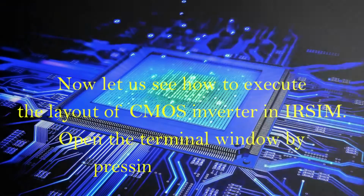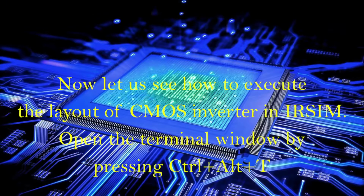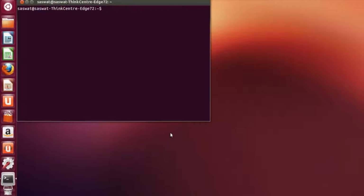Now let's see how to simulate the layout of an inverter using IRSIM. So open the terminal window by pressing Ctrl Alt and T. Open the layout file by typing magic inv3.mag. This was the layout that we had drawn.